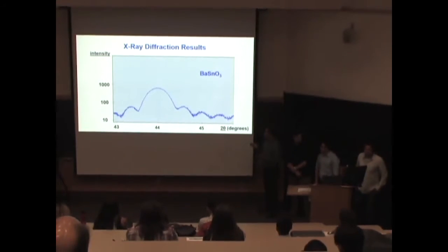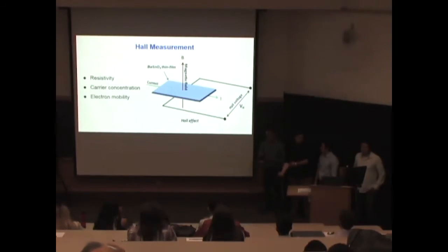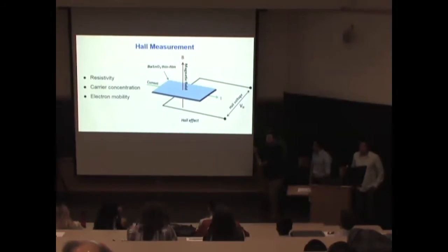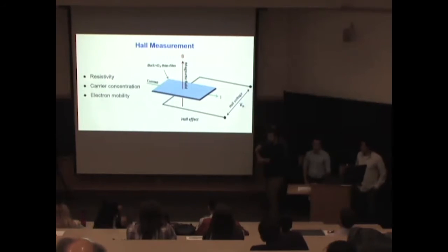As you can see here from this image, it's a 10 by 10 micrometer area, pretty small. Also, as you can tell from the picture, it is uniformly colored, the same gray color, which means our surface is smooth, great for research use. If it comes out blotchy or uneven in color, it means that our surface is rough, so we won't want that. The white specks that you see on the area are just dust particles that made their way onto our sample as it was being transferred onto the machine.